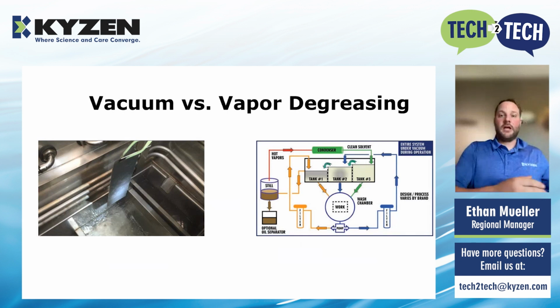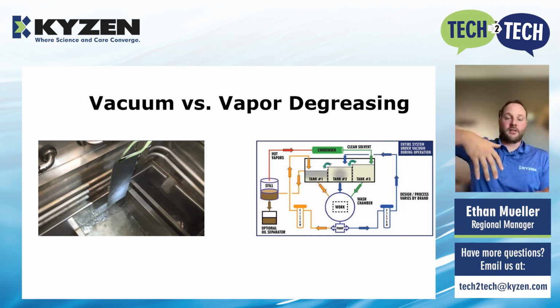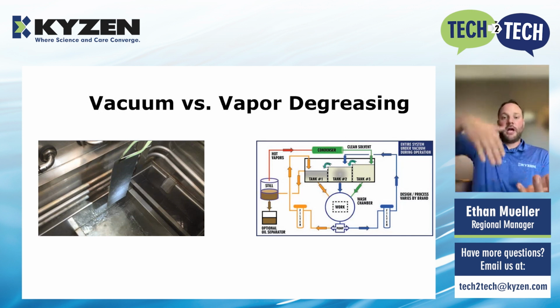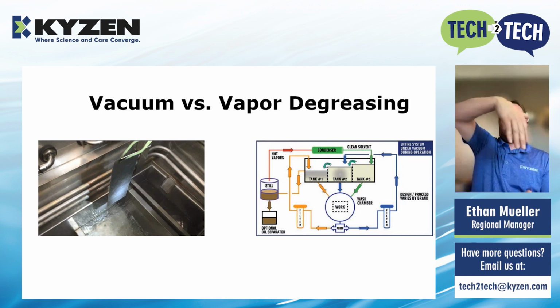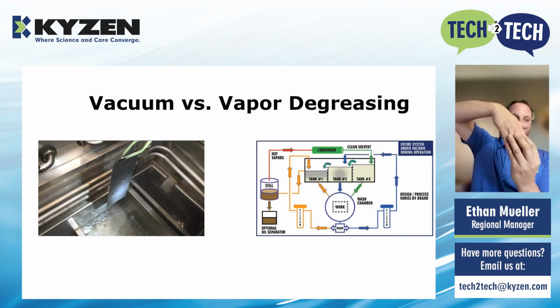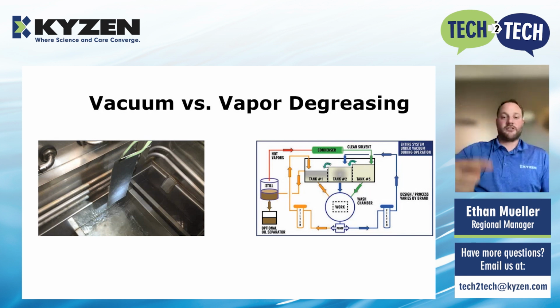There's vacuum degreasing and there is vapor degreasing. Vapor degreasing is a traditional method where you are putting a part down into an open top degreaser. There's heating on the bottom. It's boiling the solvent, turning it into a vapor, and then coming up to the part, which is in a cooled area. There's refrigeration coils around the part, and it's coming up, it condenses on the part and drips back into the machine, and it just kind of does that repetitively, and there's a process.